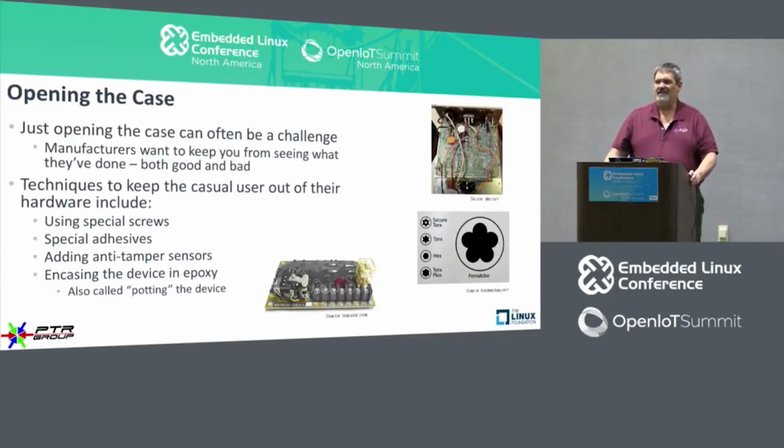What they'll have is a case that has some special switches inside of it, that if you open the case, it triggers the switch and zeroes out the flash. That is particularly troublesome. We'll talk more about that in just a minute. And the other trick that they do is encasing the device in epoxy, otherwise known as potting the device. That's that black gooey thing that you see right there.